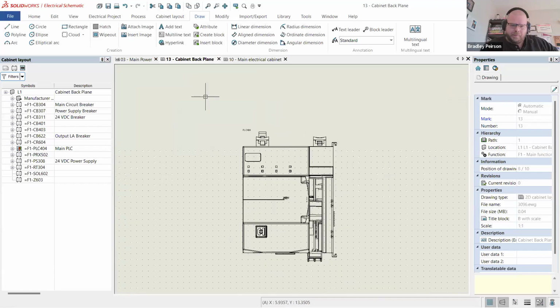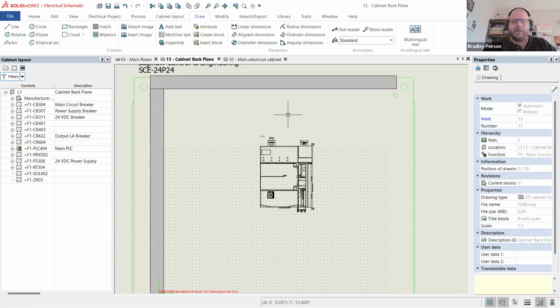In the manual for this PLC, one of the manuals, they have technical manuals and user manuals and all kinds of manuals. Somewhere in their documentation, you will find keep out distances from ductwork and from other components. Other components do not count the I/O cards, because the I/O cards have to slide up tight. That's what they do. But it has minimum keep away distances from other components, including duct.